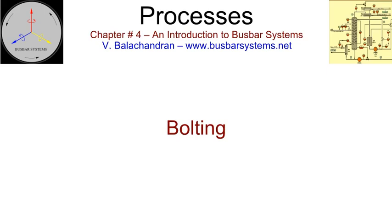These joints have been in the industry, giving satisfactory performances in onerous service conditions for a sufficient length of time to give confidence to engineers. An efficient joint must have a low contact resistance, maintain its integrity during its life by containing the effects of corrosion, fretting, thermal cycling, differential expansion, vibration, and fatigue.